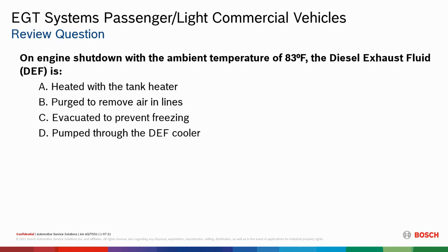So on engine shutdown, heated with the tank heater. I haven't heard of anything that heats up the fluid for any reason other than those heaters. But the tank heaters are not to heat the fluid up, we're just thawing the fluid. And purge to remove the air in the lines? We do purge the air in the lines, but not on engine shutdown.